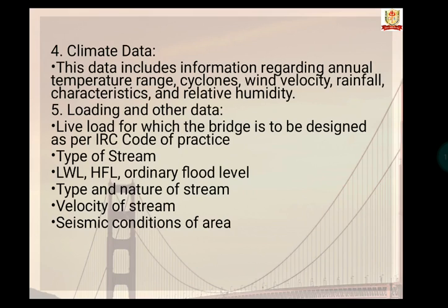Next is loading and other data. Live load for which the bridge is to be designed as per the IRC code of practice. Type of stream, high water level, low water level, high flood level, ordinary flood level, type and nature of stream, velocity of stream, seismic condition of area.